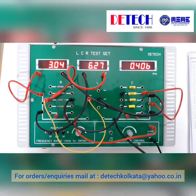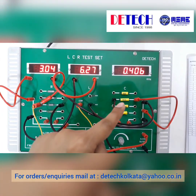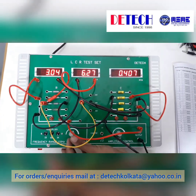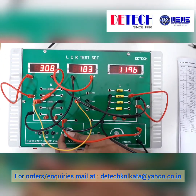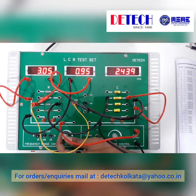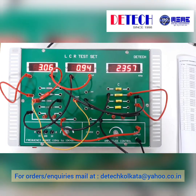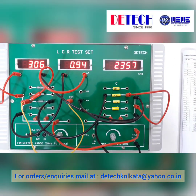Here we have connected R as 470 ohms, the inductor is 150 millihenry and the capacitor value is 0.03 microfarad. So we have set the input voltage at 3 volt. The current is 6.27 and we have started to increase the frequency. Current starts to decrease. We will find the point where it is minimum. So if we theoretically calculate it, it comes to 2.4 kilohertz, and practically also we are obtaining 2.35 kilohertz, which is very near to the theoretical value.